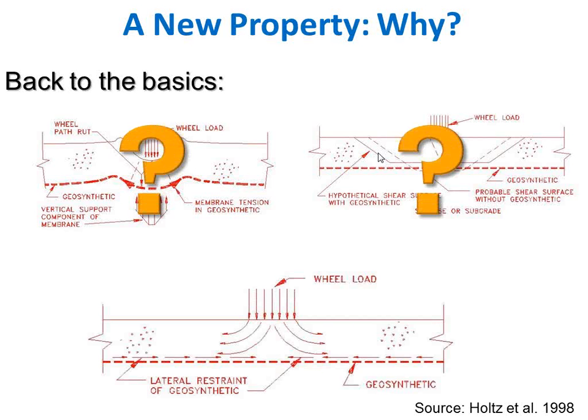And what this does is essentially it says that your pavement, you design pavements much more than certainly I do, but we want a stiff system. Well, all we want is to add stiffness. So with this lateral restraint mechanism, the reinforcement will prevent or minimize the distension of the base.